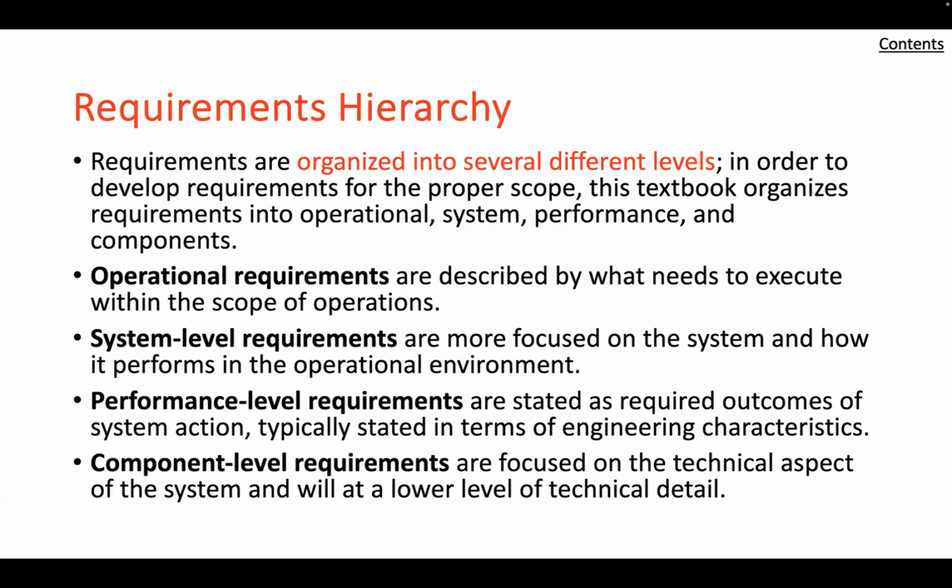These requirements may also be concerned with the design aspects in order to ensure that the performance criteria are met. Similar to the system level requirements, these are highly quantitative in nature and will come with some expected performance under defined conditions. Reliability may also be focused on the component level in order to determine if the entire system reliability numbers are achievable.